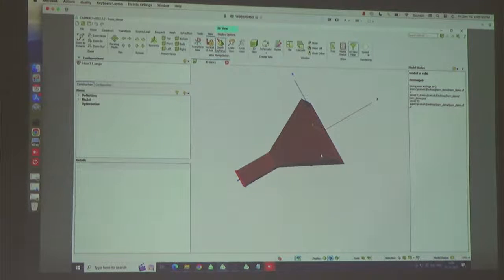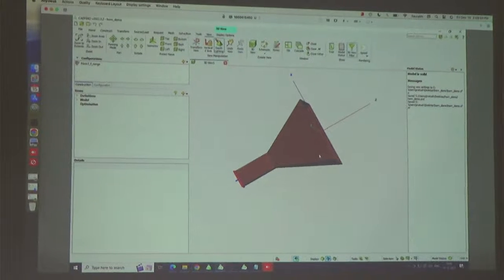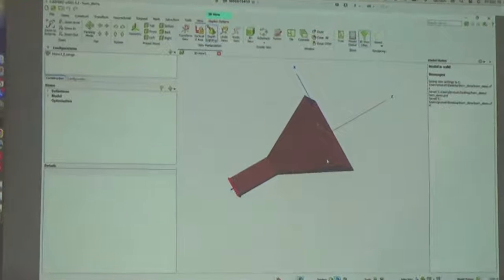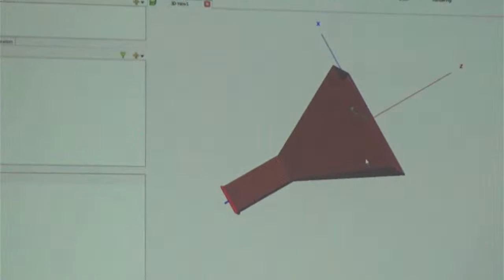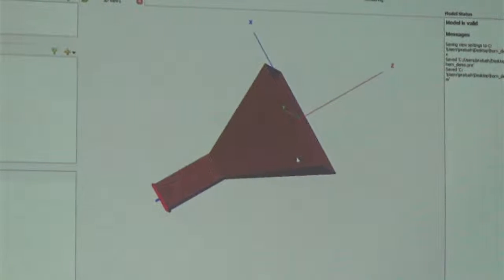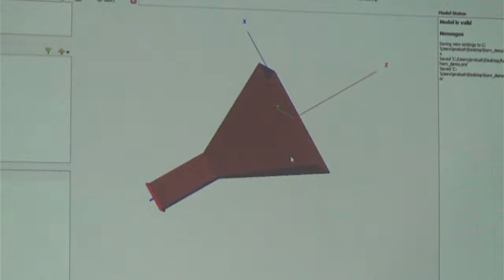This meshing is not very different from what you have studied for the 21 centimeter modeling. You basically solve your electric field at each of these mesh points, and there are various ways to do this. Essentially, all you are doing is solving Maxwell's equations and producing the electric field distribution on the surface. Your antenna properties are all derived from that. We'll touch upon that, but this is just a practical demonstration.